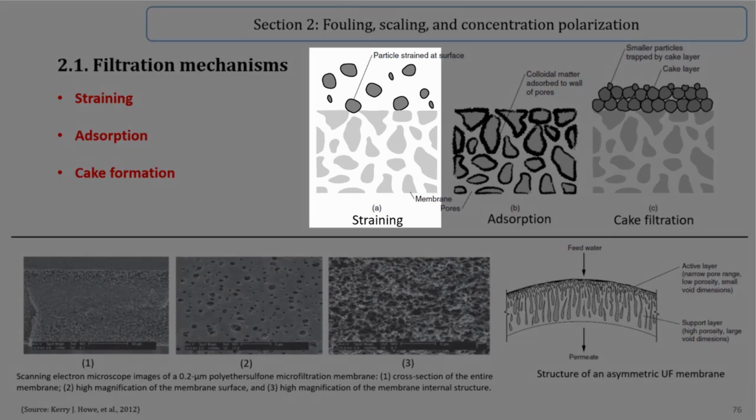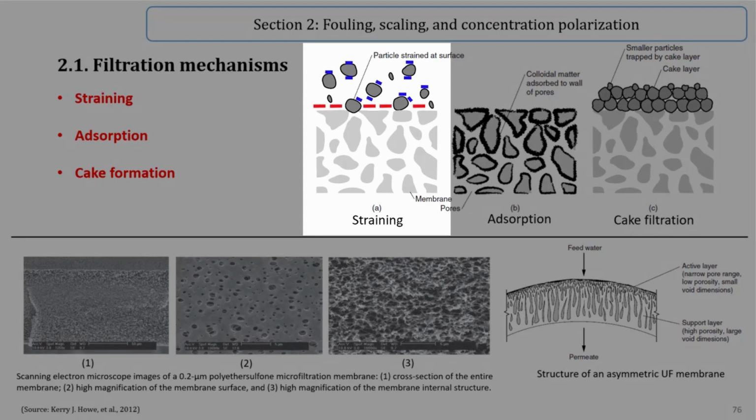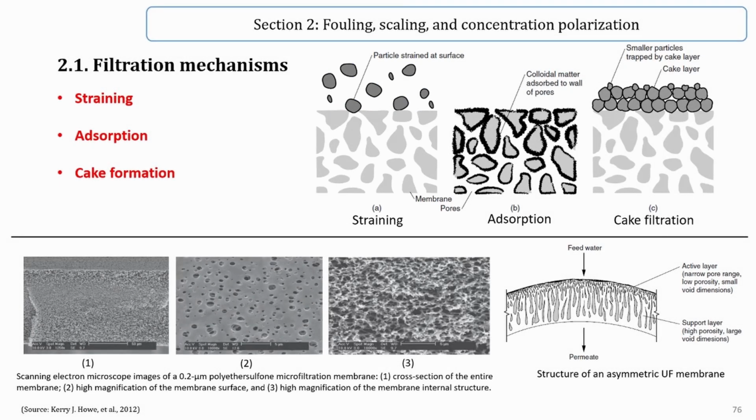When particles are near the pore size rating of the membrane, however, a fraction of the particles will be captured, resulting in particle removal. Partial capture is caused by the variability of pore size dimensions, non-spherical shape of the particles, and other interactions such as electrostatic repulsion. Typically, both particles and membrane surfaces are negatively charged. Electrostatic interactions may prevent the particles from entering the pores even if the physical size would permit passage.